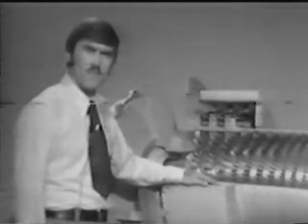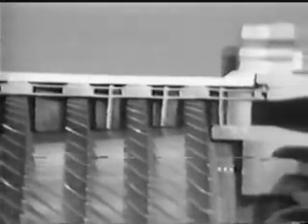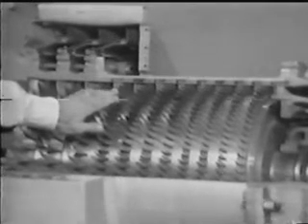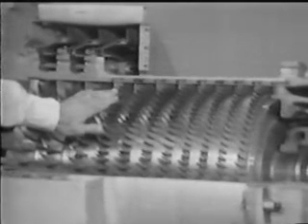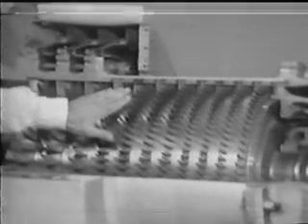To begin the process of energy production, air is first drawn into the compressor, where rows of blades compress the air into an increasingly smaller space. Energy to turn the compressor is first supplied from the external start system until the turbine has enough power to turn the compressor over by itself.